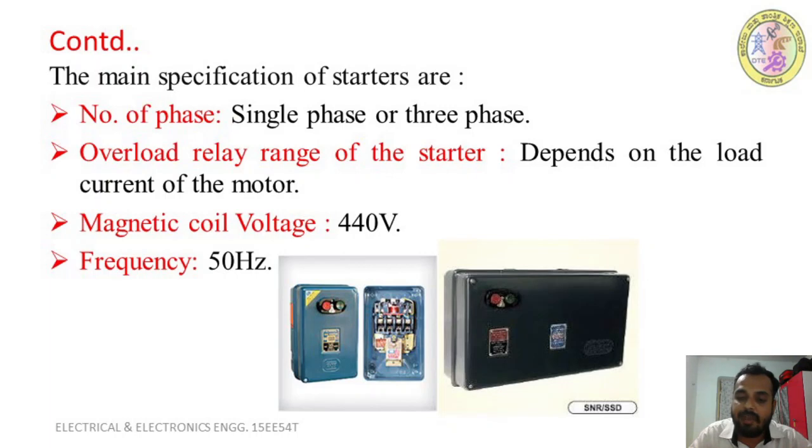So next we have seen power capacitor. For example, any induction motor causes a low power factor. To improve that power factor, we are using the power capacitor. The rating of the power capacitor depends on the size of the induction motor or HP rating of the induction motor. For every 2.5 HP, we are using 1 kVAr capacitor bank.